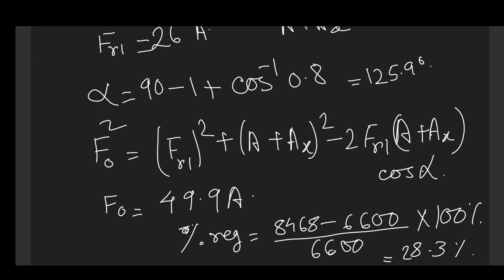You are assuming linear relationship. And here what you are doing actually, you are replacing an EMF by MMF. So you are doing just the reverse thing, and that is why if the previous one was pessimistic, now you are going to get an optimistic value.